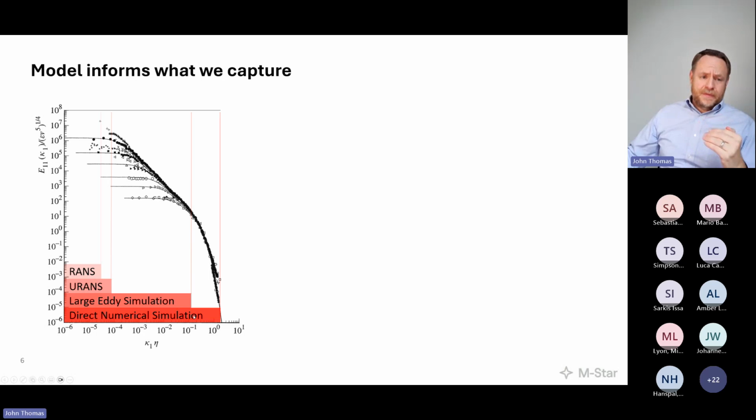As a step up from this, and we can do DNS simulation in M-Star practically, and I'll demonstrate that today, well through the transitional regime into low turbulence at industrial scale, I'll speak to here momentarily. To bend a corner, make these things a bit more tractable, it's routine for us to go on to large eddy simulation.